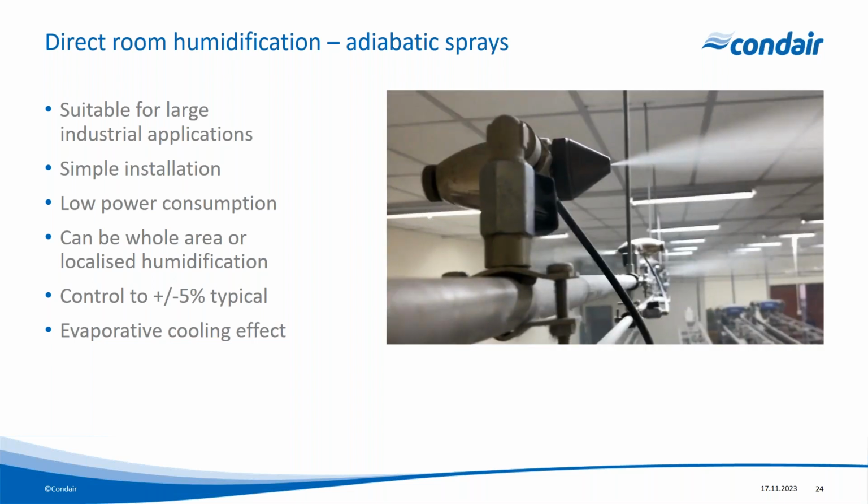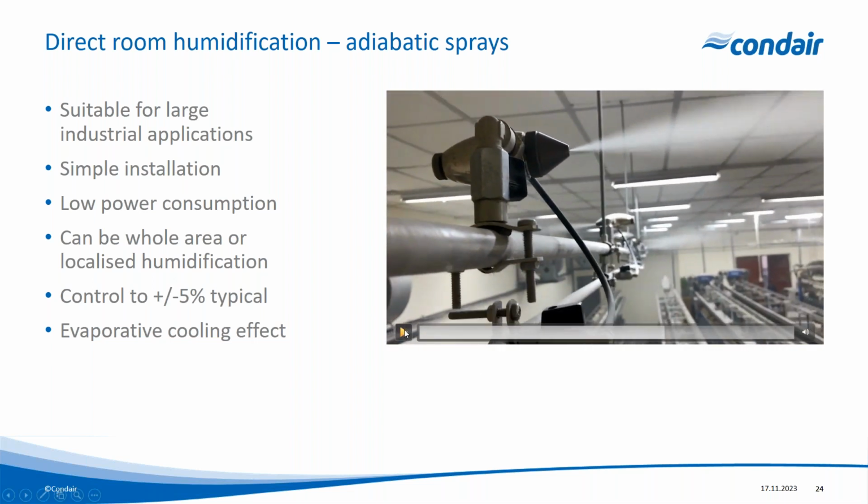Or on the different types of systems, this particular system is a compressed air and water system. And this uses compressed air to drive air and water through a nozzle. This type of system is typically used where we don't need to worry too much about dust falling into the area. Perhaps it's not so clean an environment. This is quite useful because we can use mains water in a compressed air and water system. So you can have a more efficient water usage system.